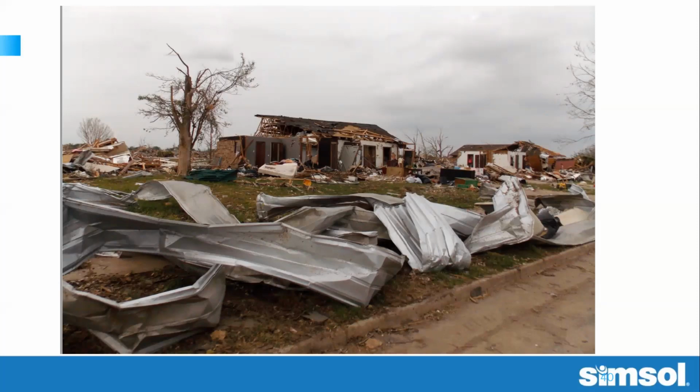I saw a lot of even wind-rated garage doors. People paid thousands of dollars for a wind-rated garage door. However, the garage door wasn't installed properly. They hung the garage door from the old framing that wasn't attached properly. So all you ended up with was a beautiful, expensive wind-rated garage door in a pile out in the yard. Metal roofs, again, were the same thing. If the metal roof was installed properly, it did very well in Michael. If the metal roof was not installed properly, it ended up in a large sheet two or three houses down.